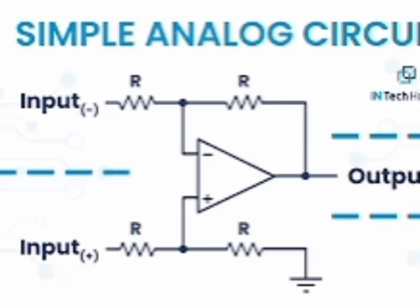Frequency at which the short circuit current gain becomes unity: FT equal to F beta root over (HFE squared minus 1), or FT equal to HFE into F beta. FT equal to HFE by 2 pi RB dash E into (CE plus CC), or FT equal to GM by 2 pi into (CE plus CC).